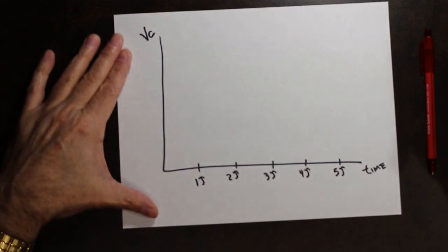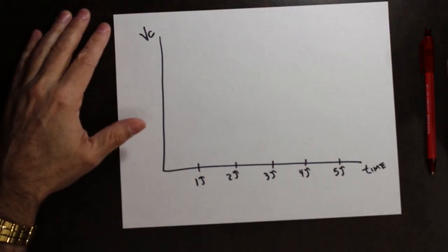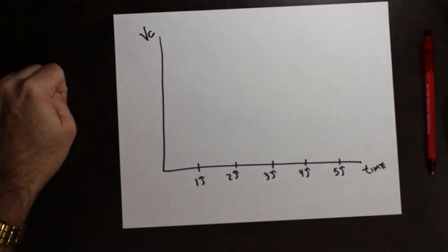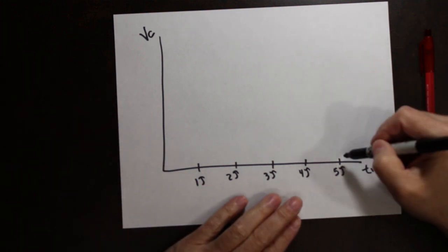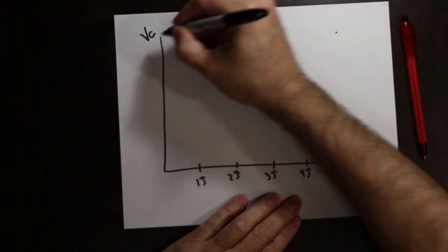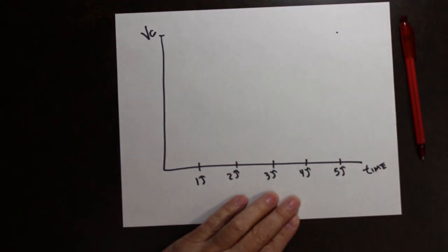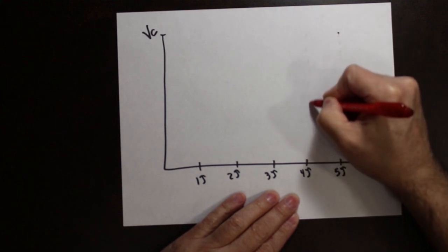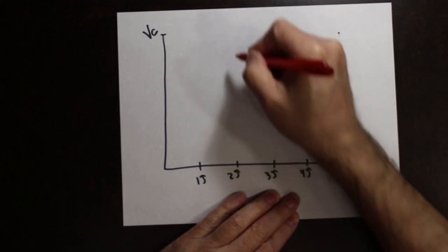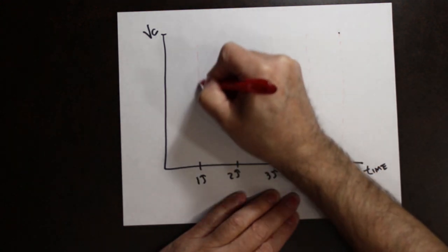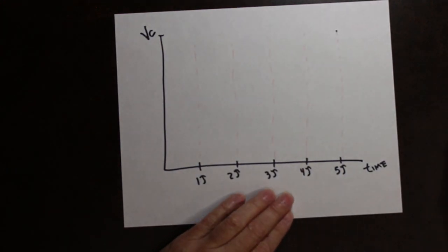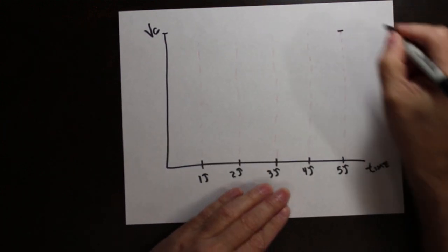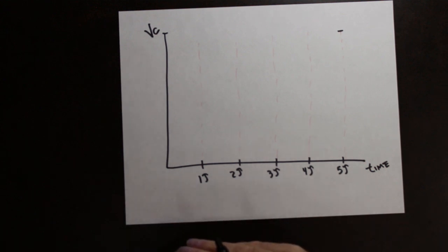Again, tau is a measurement in seconds, and it's based upon the R value and the C value. So, we know that full charge pretty much will happen at 5 tau. So we'll just go here, 4 tau, 3 tau, 2 tau, 1 tau. So we know that full charge will happen here. So that's actually about 99% full charge value.